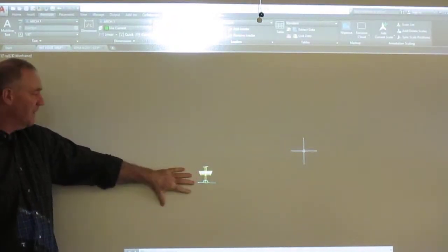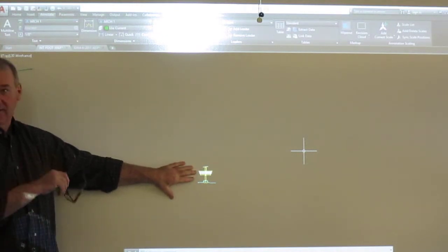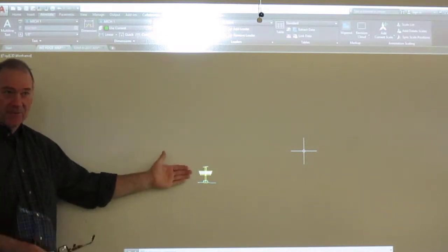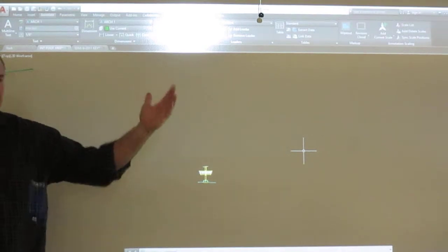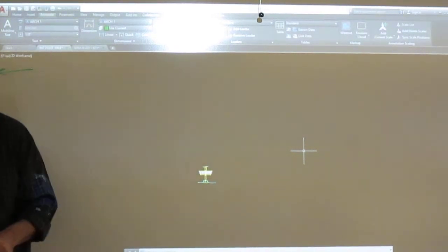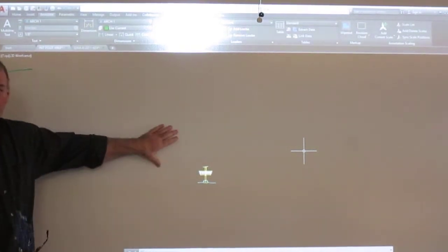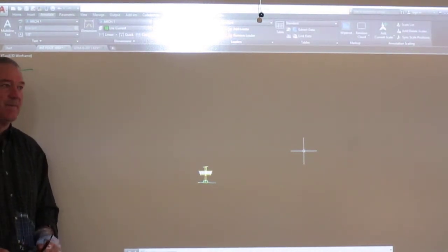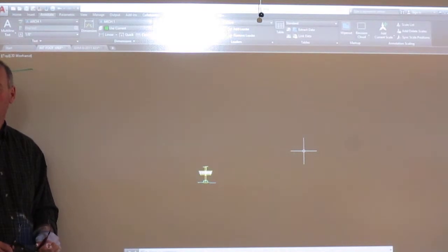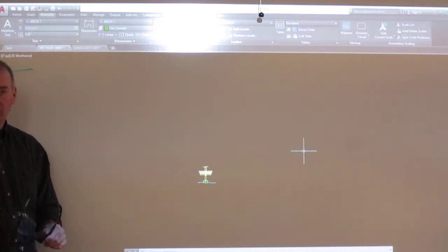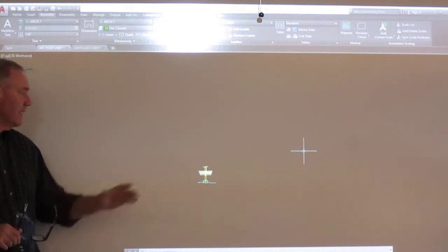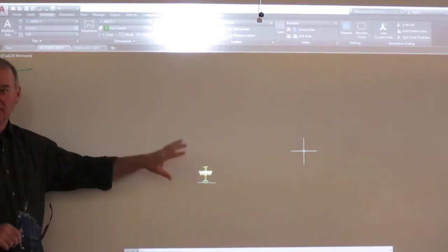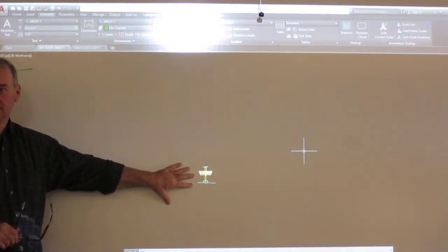I can drop this in any drawing, and then I can print it at 1 inch to a foot, I can print it at 3/4 to a foot, I can print it at 1/16 to a foot, whatever. I have a lot more flexibility with this one on the print process. But you want to make it architectural, so you want to do 1 inch to 1 foot. Well, we're gonna get there. All right. So just draw it out 1:1 in this drawing. Save it, you're done. Are we good with that?